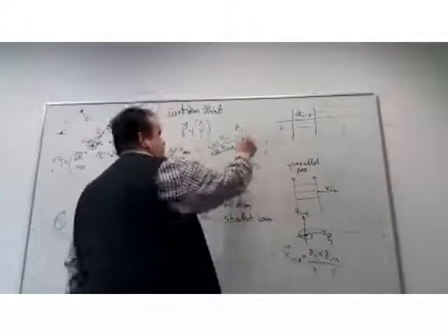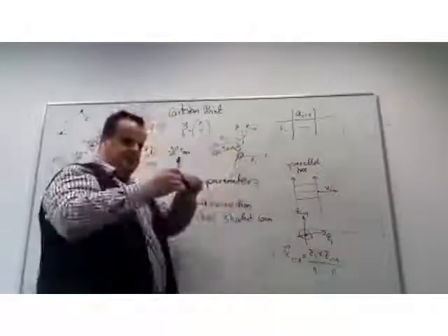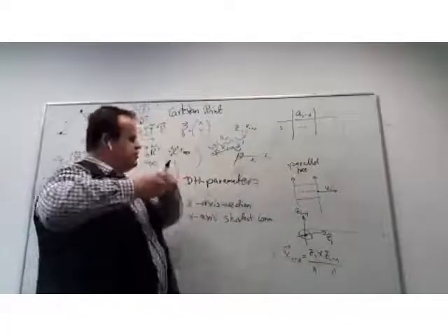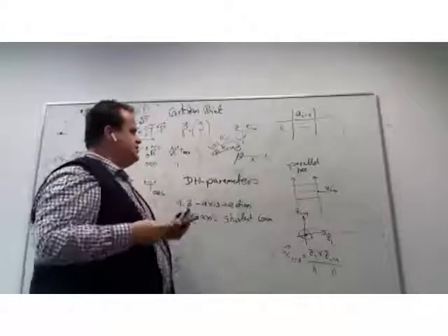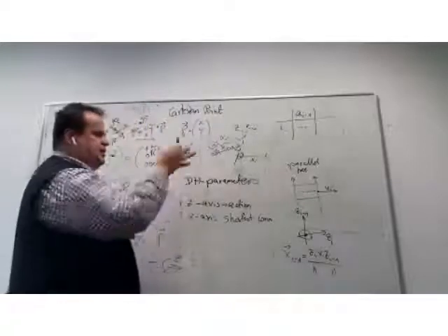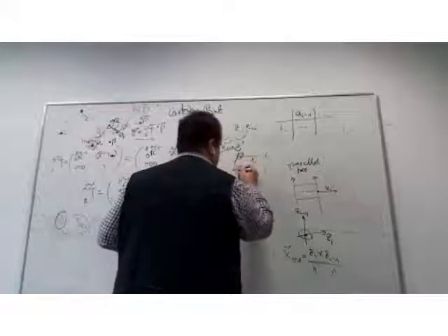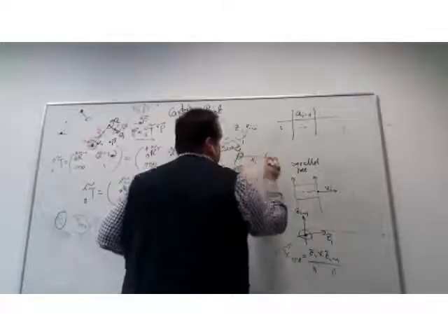The zi minus 1 and the zi axis may be rotated to each other, and the only rotation we have here, since x is orthogonal to both, is a rotation around x by some angle alpha i minus 1.